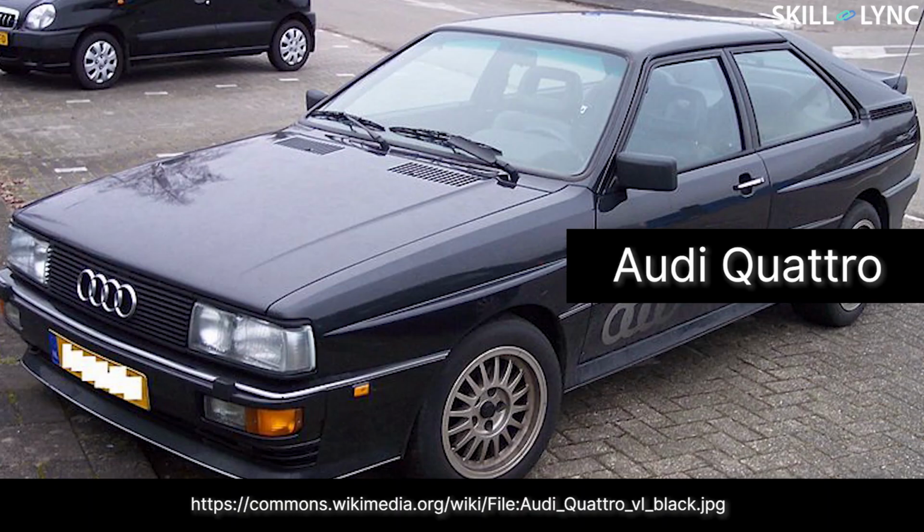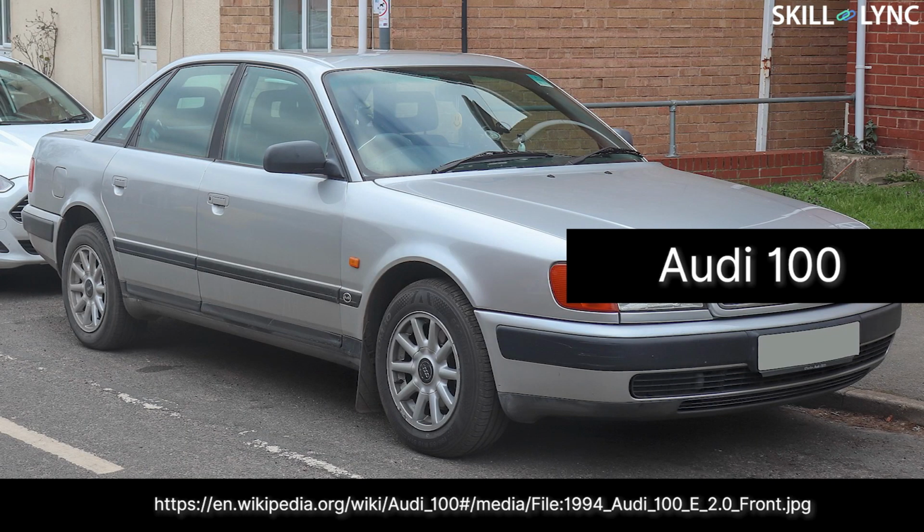The advantage of Torsen is that it works instantaneously when a wheel slips, and it has less wear when compared to the other types of LSD. This Torsen differential is being used in Audi Quattro, Audi S2, Audi 100, etc.